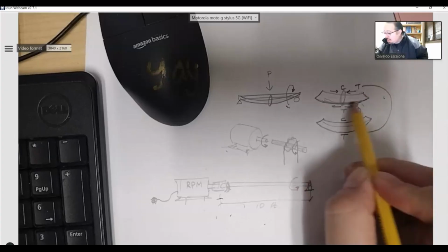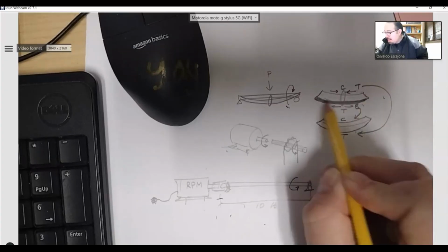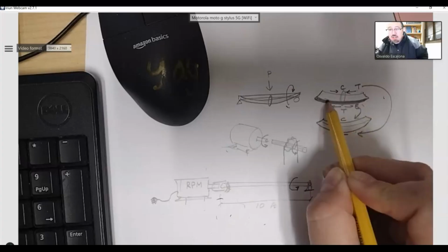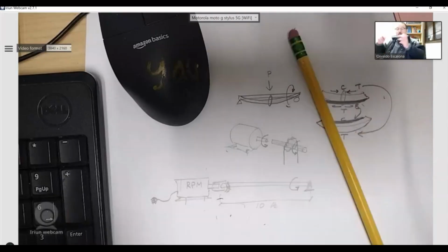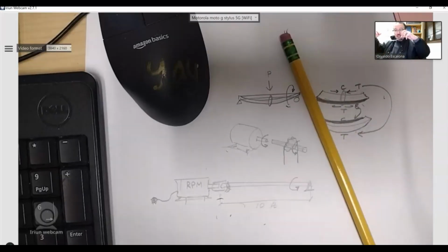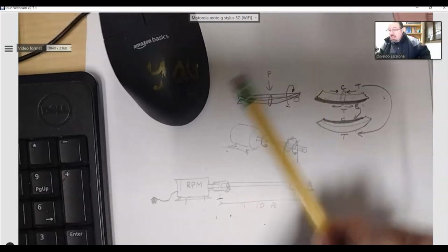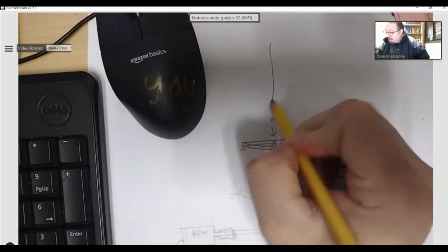But I want you guys to notice the stresses. The bottom stress was on tension. And when it flipped to the opposite side, then it became compression. Why? Because I have my ruler that is doing this, and then it flips, and whatever was the top now becomes the bottom, and it flips and flips, and I get tension and compression forces.